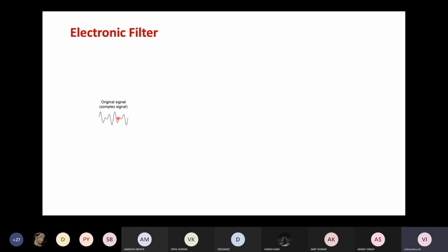So this is the original signal. This is kind of a noise signal, and it's just a random signal. If we break this signal into various components, or if we do the frequency decomposition of the noise signal, this is how it looks. So this signal will have components with low frequency, medium frequency, and high frequency as well. So this is a combination of signals of various frequencies. Okay. So this noise signal can be equivalently written as a combination of these signals.